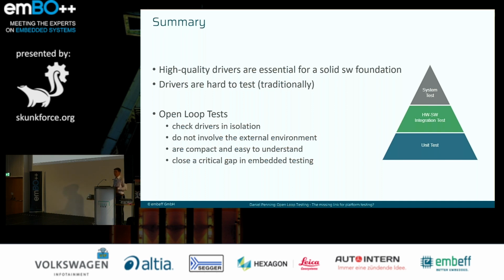So what did we see? I hope we can all agree that for solid embedded systems, we need a good foundation. We need good hardware and we need good drivers to make this work. And I reasoned about why drivers are traditionally very hard to test. There's a lot of manual process involved in practice. If you right now go ahead, test it without open loop testing, it's a lot of work. And open loop tests provide an alternative to system testing, or an extension to system testing. You can do this as a developer. So while writing your driver, you can start writing tests against it. So you can do test-driven development with this approach for your driver, hardware-related code.